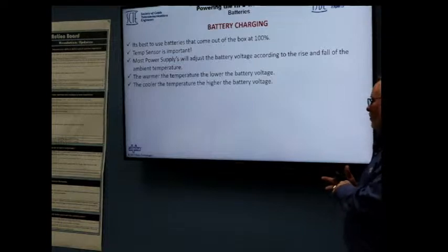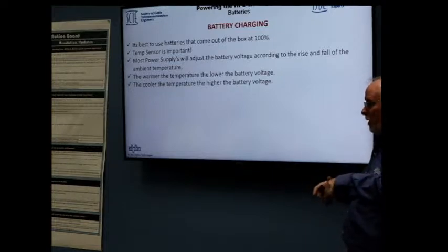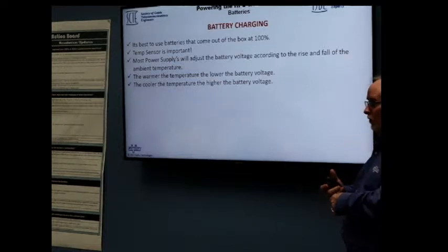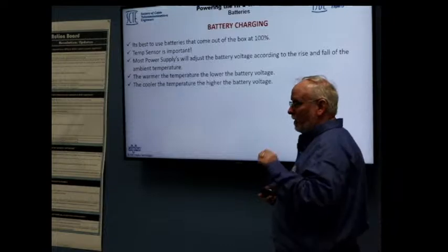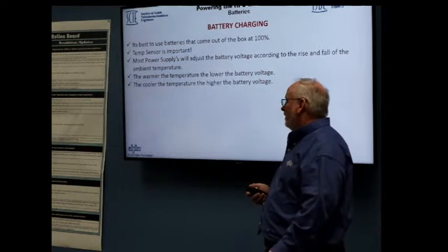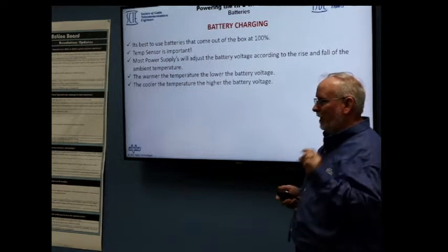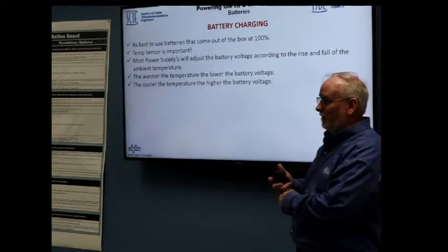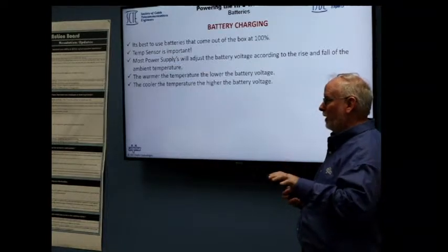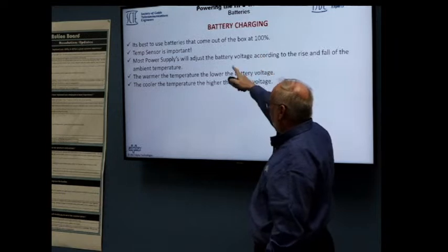If you go to Walmart and you buy a battery off the tray, if you take that battery and you charge it up at home, you will actually have a longer service life than if you just plug it in your car and start it up. If you trickle charge it, it'll actually improve the battery lifetime. The last battery I put in my car was a platinum battery of some sort, Craftsman platinum battery. It lasted me 8 years in my car. That is a very long time for a battery. It's because I charge it up, and routinely I would trickle charge the battery to full charge. It was an AGM. But again, bring them out of the box.